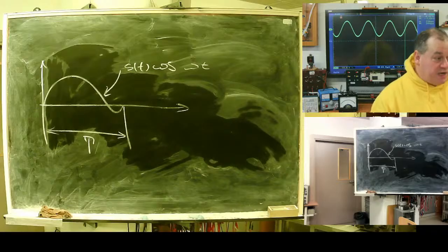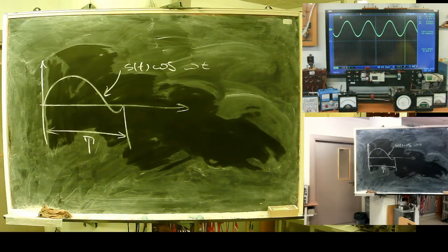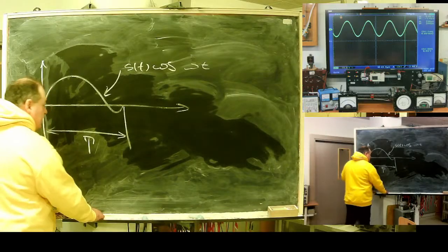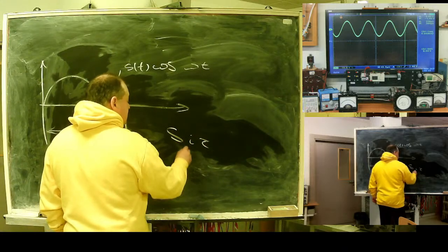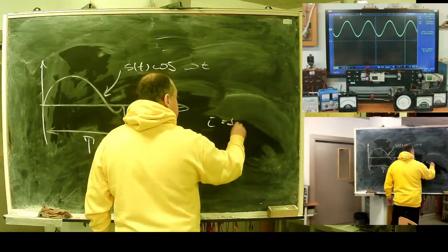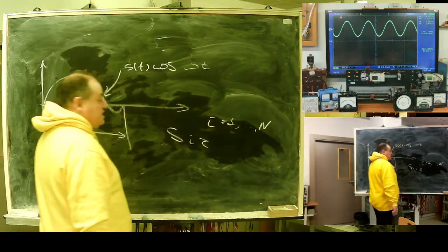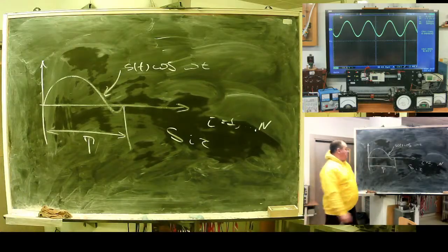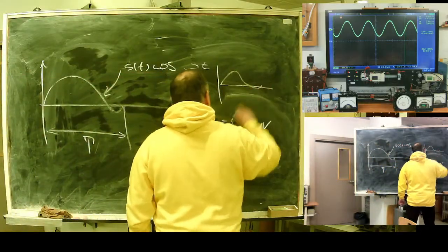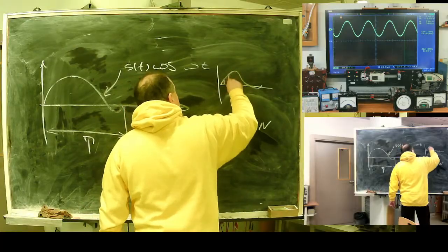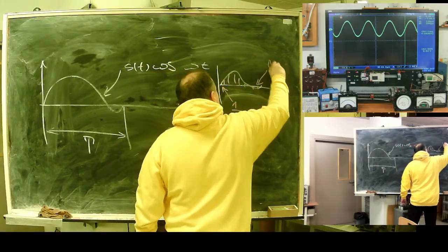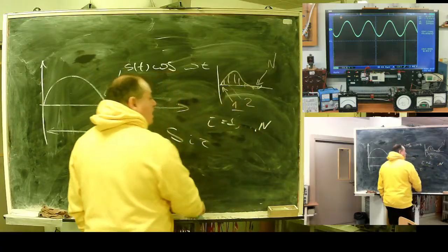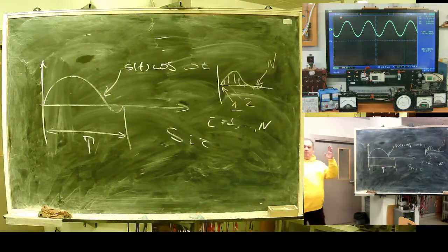I'm performing processing numerically. I don't have this time, but I have values of my signal. I have sampled values of my signal, where I start from 1 and end, let's say I have n points per period. Here are my samples. Number 1, number 2, number n. I'm operating with a sample set after analog to digital conversion.